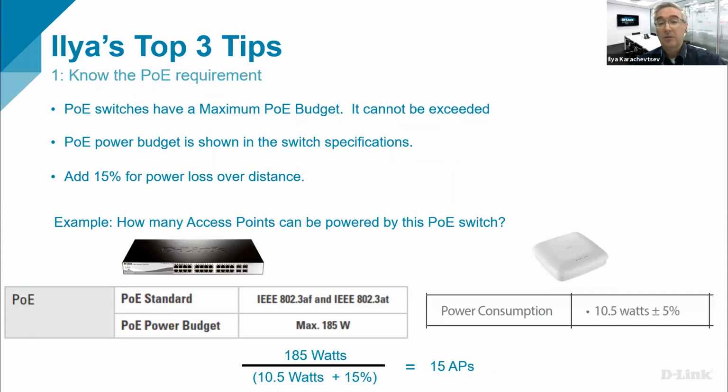So in our switches, we can also set up a PoE priority. You can prioritize certain devices. For example, if you're expecting a power shortage on PoE, and you think, okay, that access point or that camera may go down, but that device should never go down, you put that device as high PoE priority. So that's the idea behind that feature in our switches.